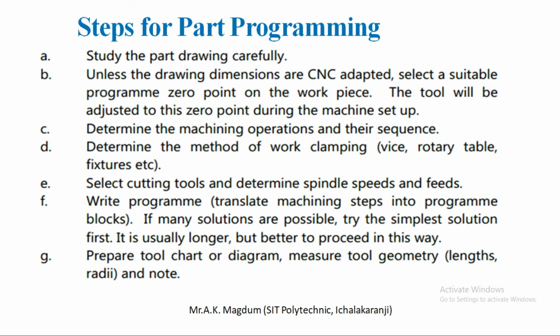Next, prepare the tool chart or diagram and measure the tool geometry, that is, what is the length and what is the radius of the tool, and note down all the dimensions in the tool chart.